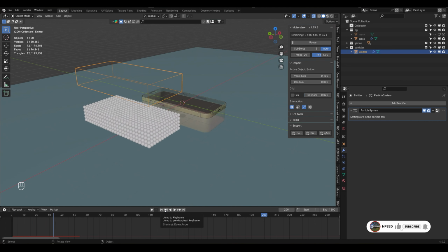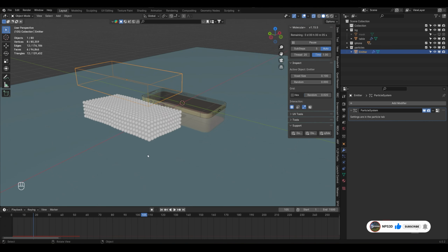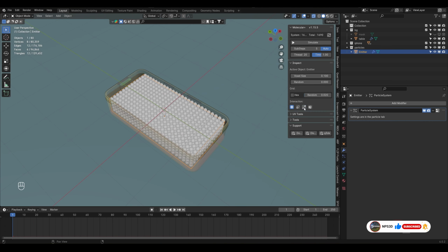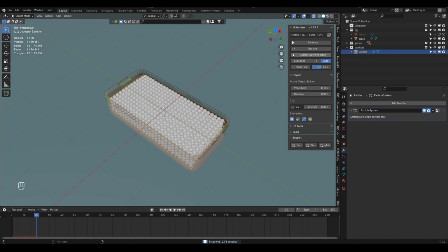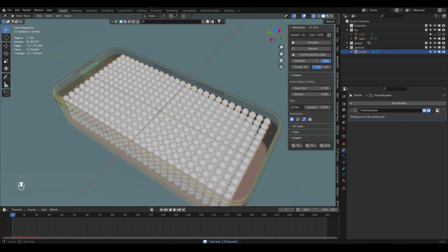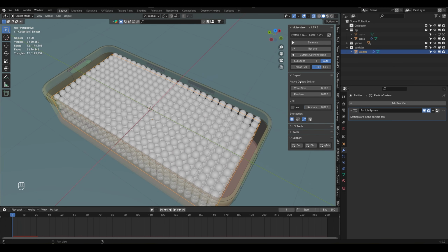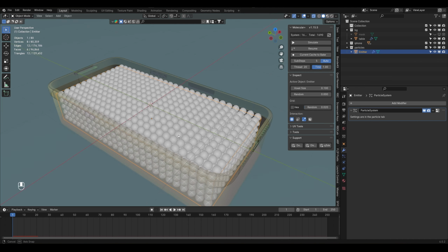You can see. So you can use both things. I will use this particle linking here as well, and let me simulate. And guys, you can also use this sub step to get more clear, clean results actually. And this time is basically where you can control the animation speed of this particle. So yeah, these are the things which you have to take care of only.